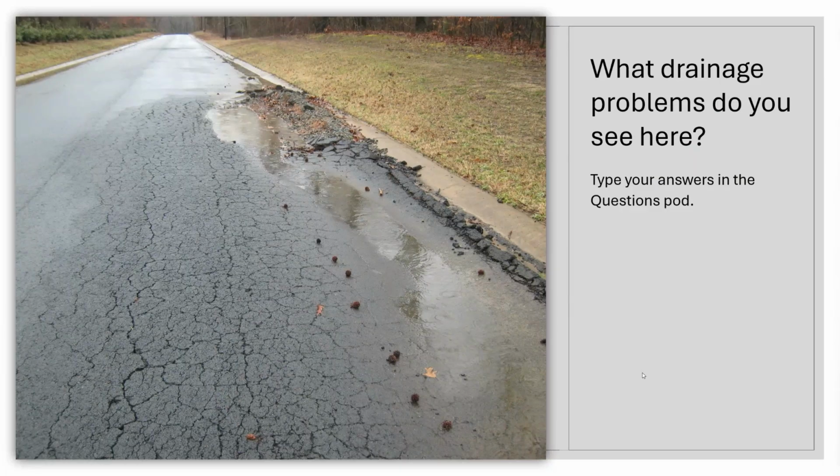Now in this particular spot, what you can see is we have curb on either side of the road, and the curb and gutter is there, but the drop inlet is way far away from this. You don't see any drop inlets in this. But the other piece that really stands out to me is that on both sides of the road, the slopes are where the road is really the lowest point around. Both side slopes, that grassy area, those both go uphill. So all of the rainfall that falls in this general area is flowing toward the roadway.